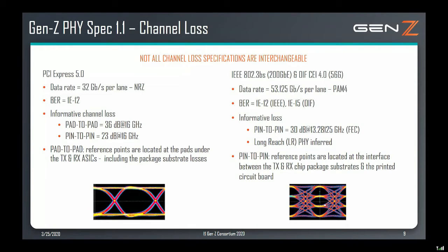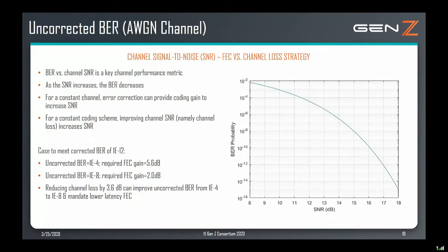Okay, and one other question pertains to this slide in particular. The question is, are the eye diagrams at TX or RX? It could be either, but this one I believe is RX. The receiver, it kind of depends on how well your receiver is equalized. If you have more errors, you're going to see fuzzier lines, and I think this one is from the receiver. Thank you. Okay, good questions.